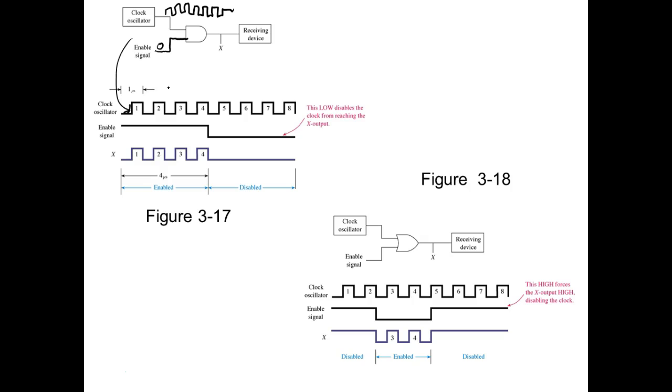Okay. So that means I'm going to come over here and somehow connect this thing to 0 volts. Not a nothing volts. It's going to be connected to 0 volts, right? You understand? So normally what we'll do is we'll connect that to circuit common, which is definitely going to be below 400 millivolts. So there's no way in the world I can get all highs, right? You understand? So what's the output going to be? It's going to be a low.